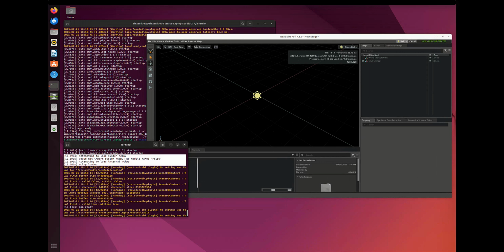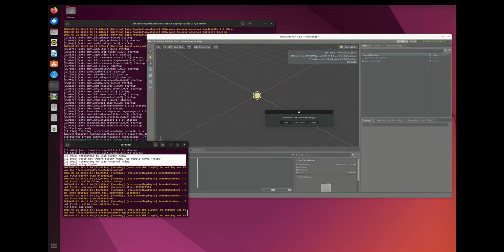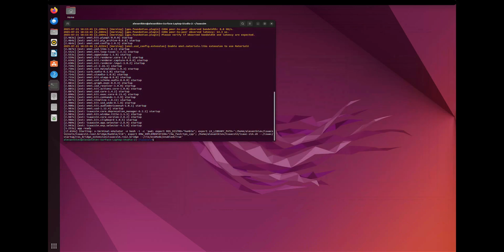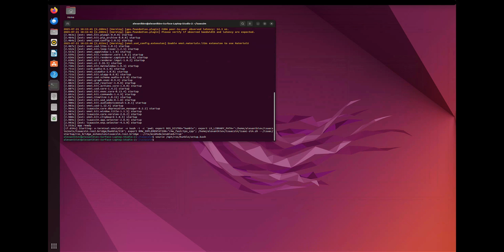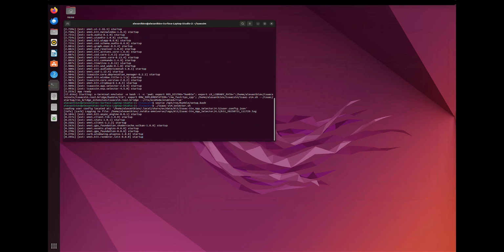To properly launch it the way we want, for all of the communication to take place, we have to source the ROS2 environment in the terminal first, and then launch the script. And then as everything works, you will see in the demo at the end of this video that the ROS2 communication and messages will be visible as a part of a ROS domain ID, which is the default 0, and